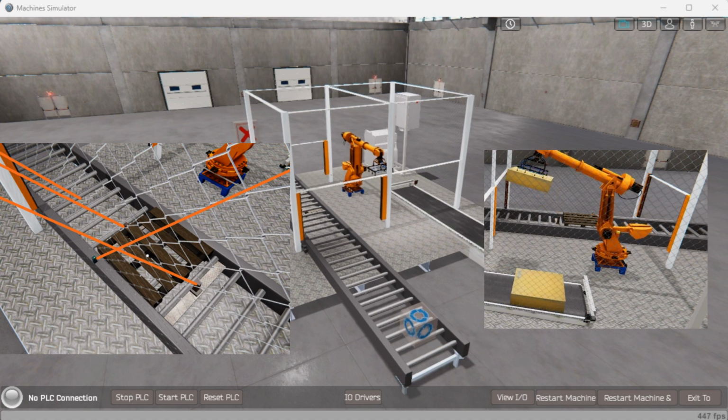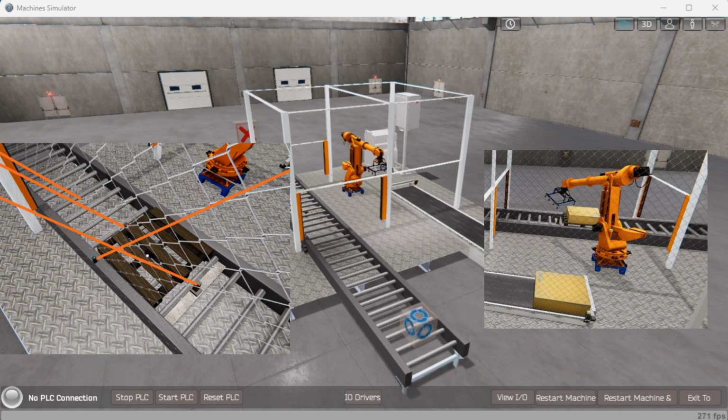Once the pallet has 4 boxes, stopper 1 will deactivate and the roller conveyor will start. This will allow the full pallet to exit the machine. Stopper 2 then deactivates and allows the next pallet to be loaded.